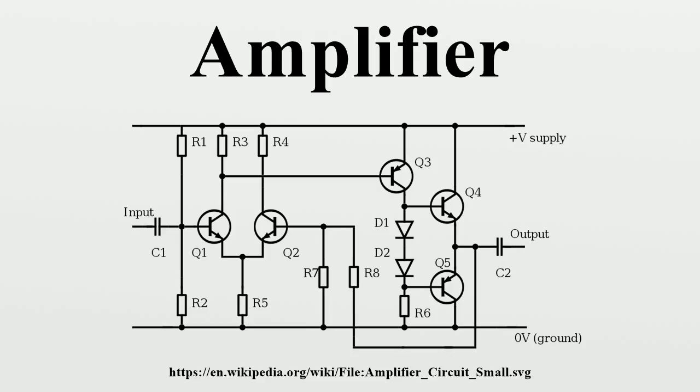Magnetic amplifiers. These are devices somewhat similar to a transformer where one winding is used to control the saturation of a magnetic core, hence altering the impedance of the other winding. They have largely fallen out of use due to developments in semiconductor amplifiers but are still useful in HVDC control, and in nuclear power control circuitry due to their not being affected by radioactivity.